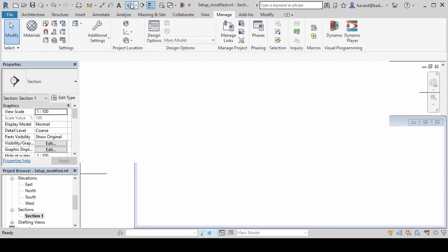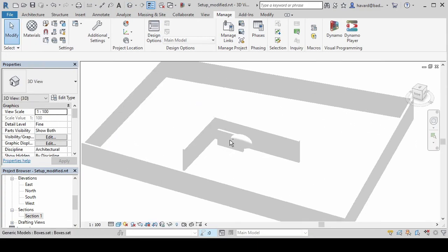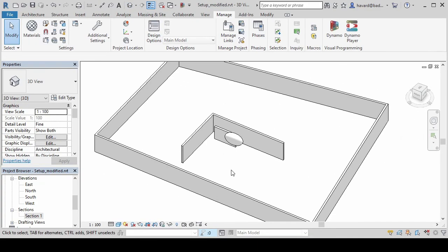All right. The last method of bringing this geometry into Revit that's going to create pretty close to native Revit family geometry, where you can also apply materials as parameters to different parts of the geometry, is going to use a Dynamo script that's going to import SAT files directly into Revit. This is going to be covered in the next section, so please keep up.